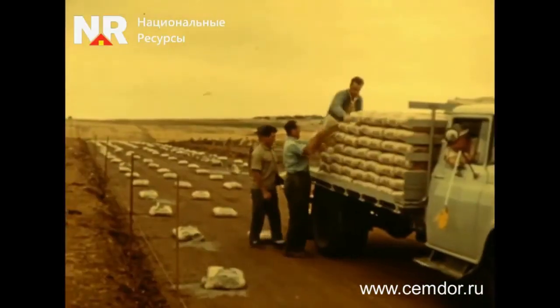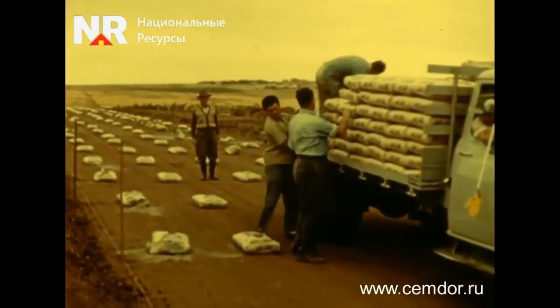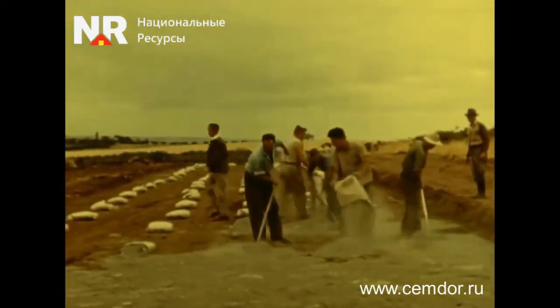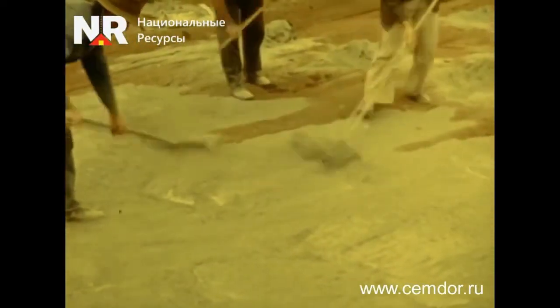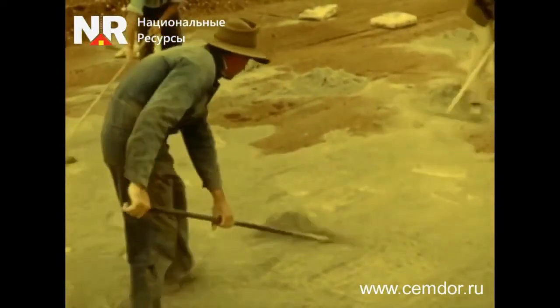The cement required for the road surface can be delivered by truck in bags. The bags are laid out along a specific route and then opened. Next, the cement is evenly distributed over the entire area of the road section under construction for subsequent mixing with the soil. The spacing between the bags is calculated based on the required cement content and the thickness of the structural layer.